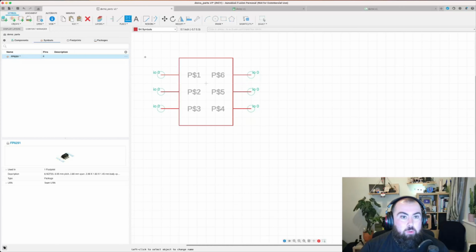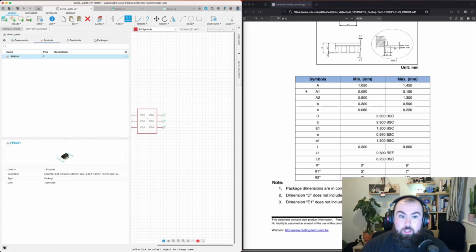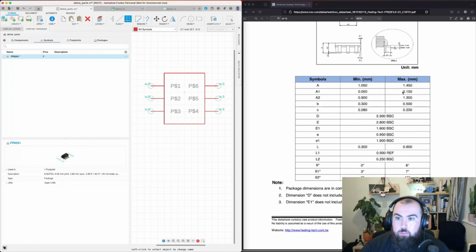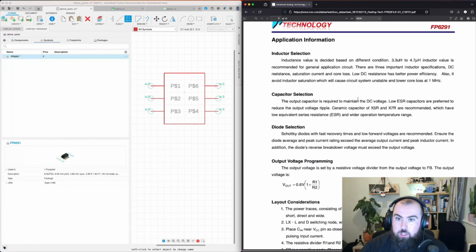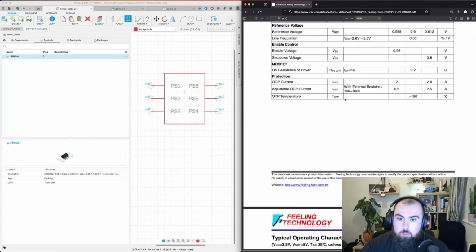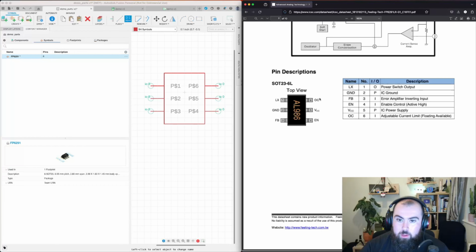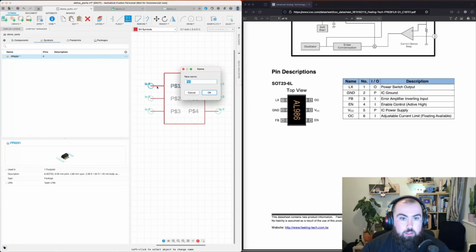So we'll go to the name button and click on the pin. It'll ask us to fill something in. If we want to know what we're actually going to fill in, we should probably look at the names that the pins have on the chip. So scroll up to this diagram. There we go. We have pin numbers here along with names. So let's just match those up. Very quick and easy. Just click and type.